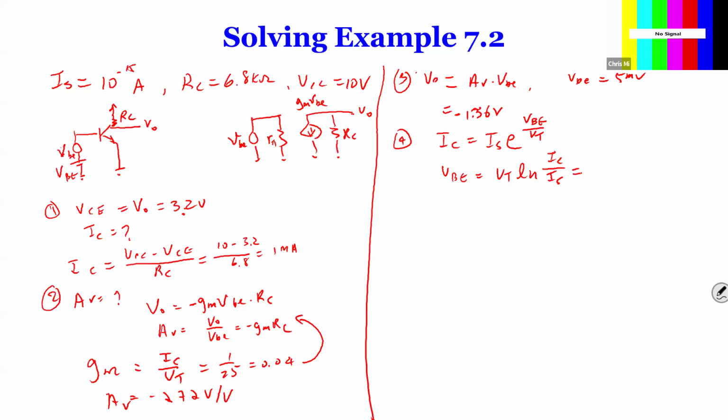And this number, I already calculated, 0.691 volt. Let's move back. So that's the DC bias? Yeah, that's your DC biasing voltage. That's your VBE. So if you look at what it says here, let's say this is your DC biasing. So your output will be something like here.